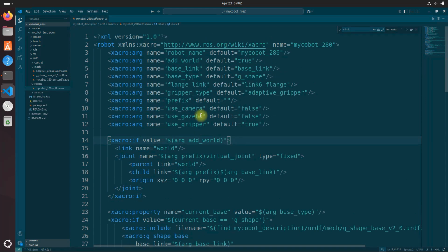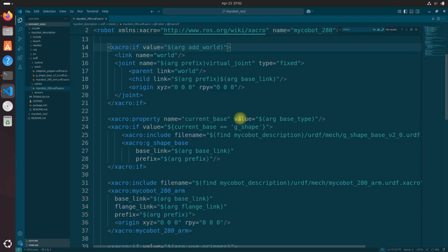And again, a very good exercise to do is to build a URDF from scratch so you understand how everything's built from the ground up. That'll enable you to more readily tweak different things in your robotic arm as you would like. When you know all the fundamentals and how it's built from the ground up, you can more easily troubleshoot and identify where things go wrong. And I've got different tutorials on my website building very basic URDFs all the way from scratch.